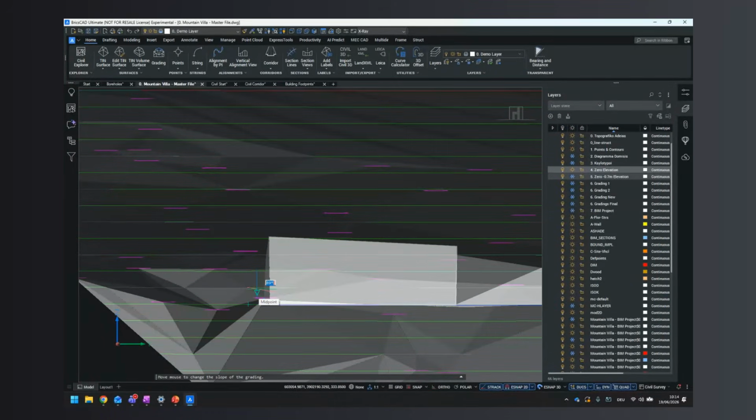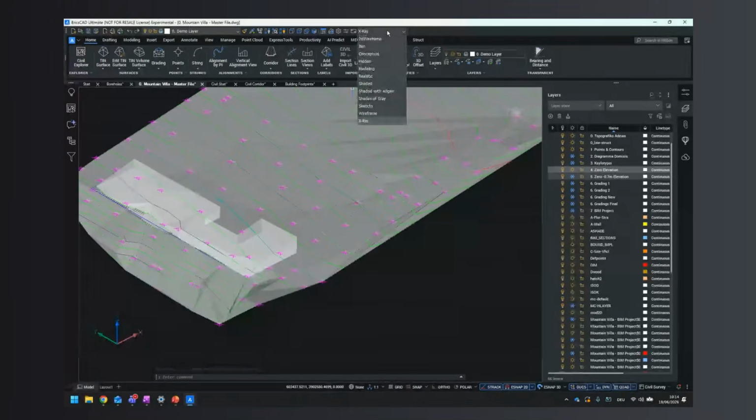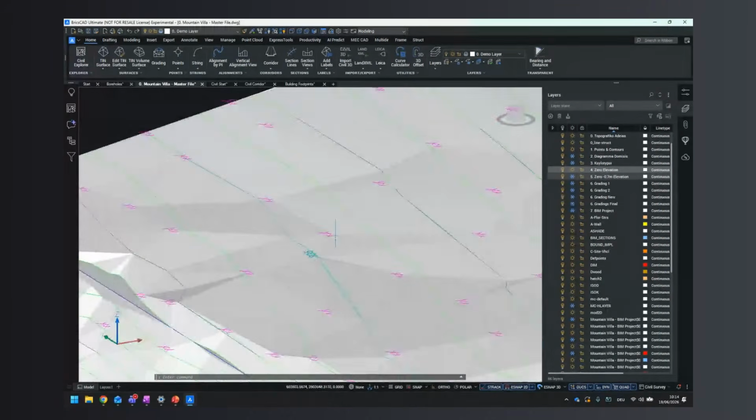Now, remember, we cannot do 90 degrees because that goes against the definition of a thin surface. A thin surface is a surface, which means that 2 points cannot have the same x, y coordinates and a different z value. So we're restricted to an 89.999 degree declination, which is perfectly good enough for the execution. I will change the visual style and see what we did.